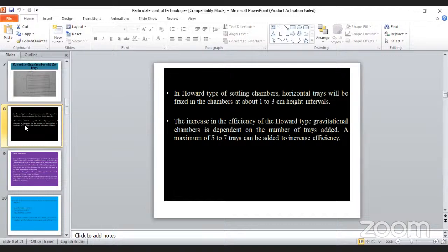It is not much height, so the flow is narrow. Whenever the flow is turned, the flow speed is reduced, and then any dense particle will automatically find a way to settle down. It is a normal scientific phenomenon.